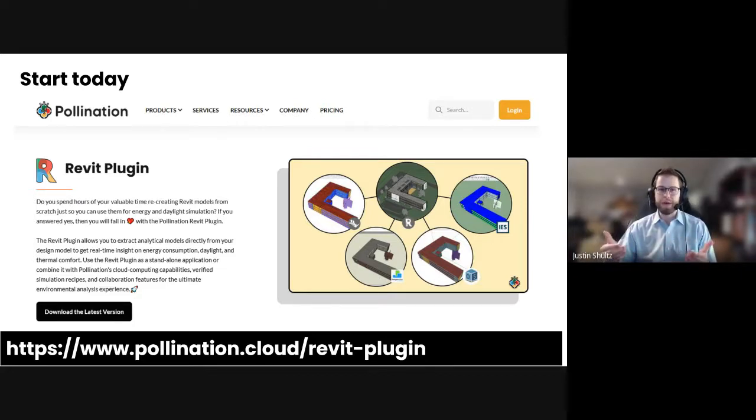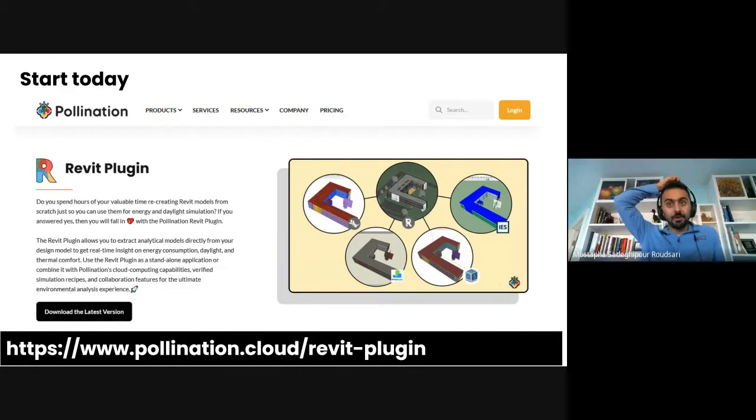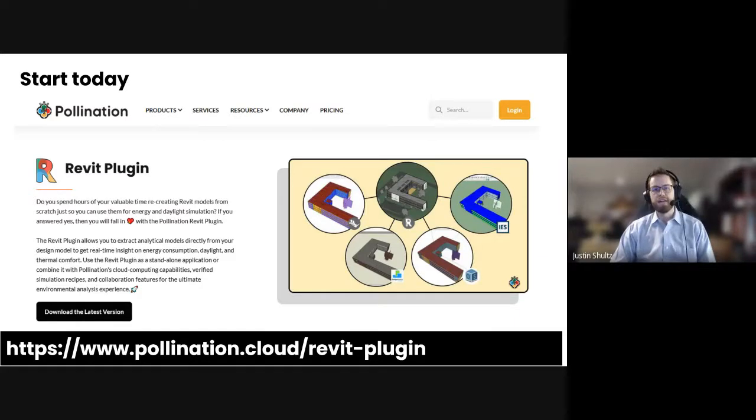And that would be a process that would be really fast to repeat, because then I could just draw all the lines, and then re-import the Dragonfly model JSON, DF JSON. Yeah, I should have just written it down. Yes, that's actually my go-to workflow. Frankly, it's a lot better than drawing all the model lines in Revit.